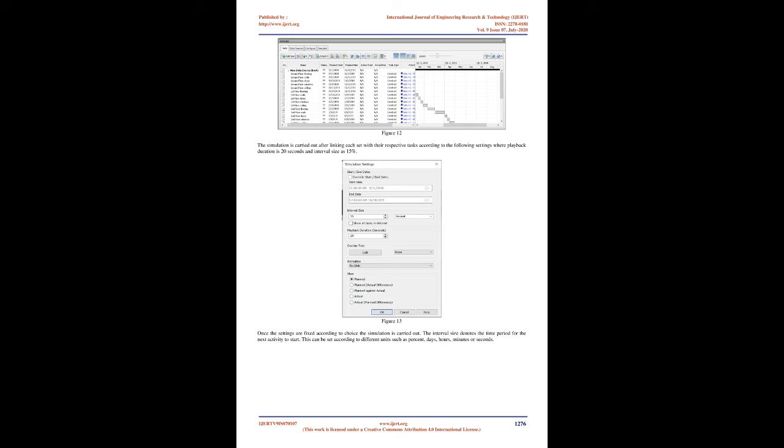Then we rebuild the task hierarchy shown in the schedule, which transfers the entire schedule and tasks with their respective start and finish dates into the software. Each task is then linked to its respective sets with the help of attachments. Once each task was linked to the respective set correctly, the task type was set to construct.